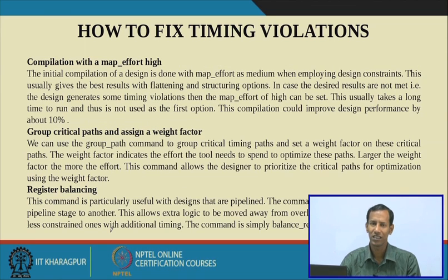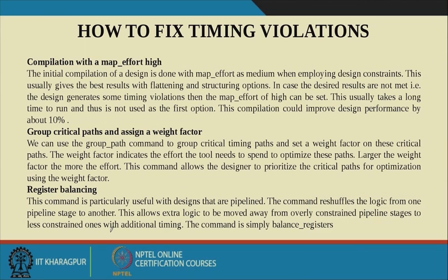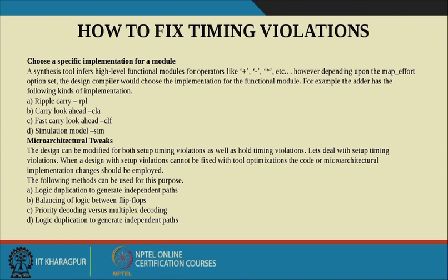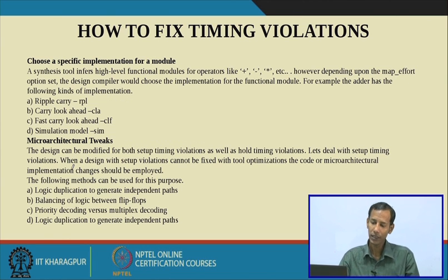So this means how you can do this compilation with map effort high, we have already said that. It means these things: register retiming and then group critical path, all these things we have seen. Then, as I said, you can choose different kinds of architecture for adder implementation.